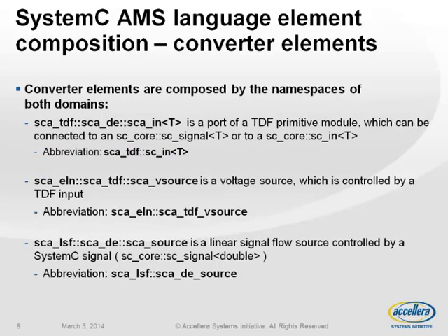And then we have in the language some elements which convert between different domains. And there we also have naming conventions. In this case, we have a port which is able to convert from the discrete event domain, that means the classical SystemC signal, to the TDF domain. That means this is a port in the TDF domain coming from the discrete event domain, and it's an input of an arbitrary type.